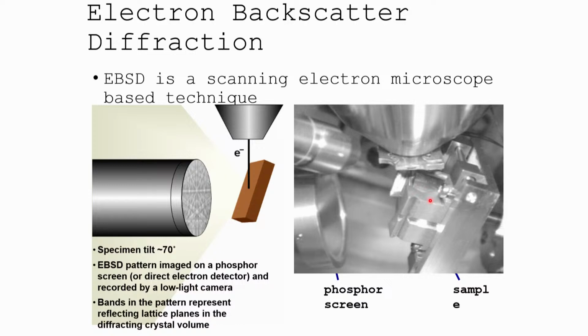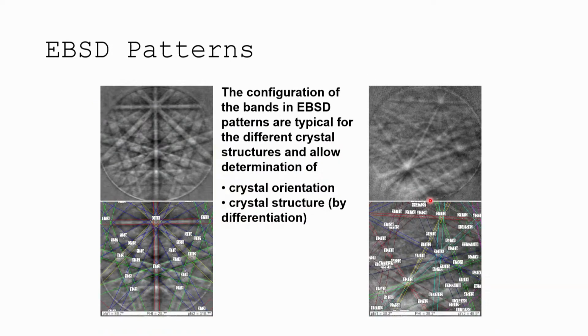And then this is just a screen of an actual SEM system. So within the pattern itself, this gives you information of how diffraction occurs within the crystal where your spot is incident. If it's not a spot and it's actually over many grains, then you won't see any pattern, right? It will be clear. It'll be destructive interference. But if you see it, then you can come in here and you can determine exactly what the diffraction bands mean. We call it index the pattern and assign Miller indices, which we're going to go over here. It will tell you what the phase is.